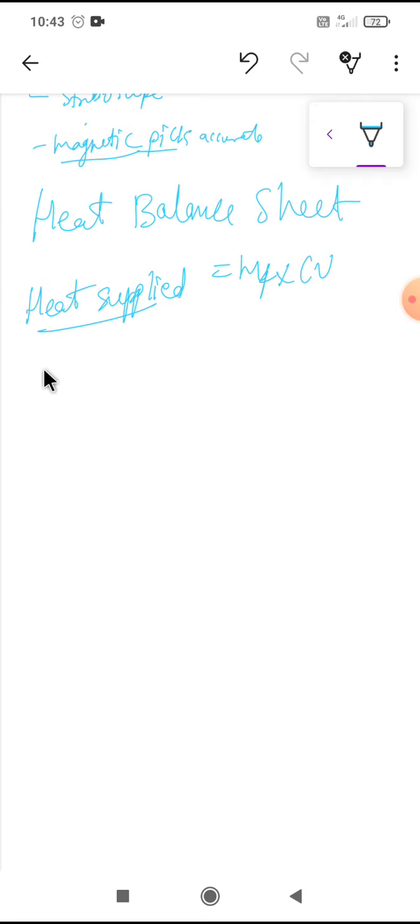So heat expenditure. As we use the word money expenditure, here we will use heat expenditure or utilized. So the heat energy of the fuel is partly converted into useful work, that is brake power, and the remainder is carried out by the cooling water, exhaust gases, and some heat is lost in radiation, incomplete combustion, lubricating oil, which remains unaccounted for. So frictional power is not accounted in the heat calculation, since friction work is converted into heat, which in turn is transferred partly to the cooling water and the remainder is carried out to the exhaust gases.